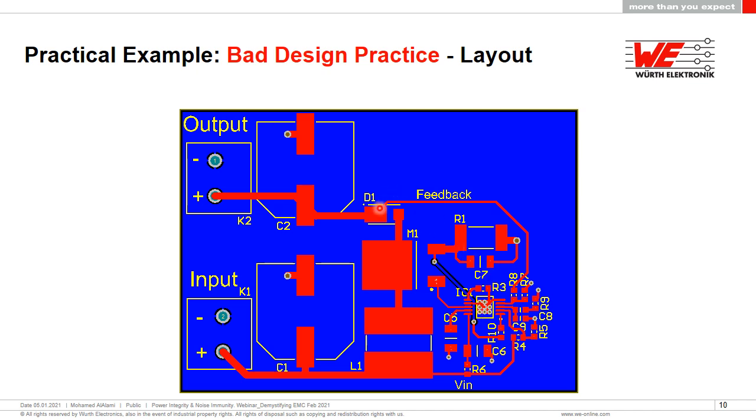That's coming from the diode. Naturally, you're better off, and the recommendation is always, to take it off the capacitor straight into your voltage divider, into your IC, to feed back the output voltage. So a few different aspects and issues. If you look more closely, you'll see some key capacitors or decoupling capacitors have been left quite a distance away from the actual IC, where they need to be as close as possible to the IC itself.